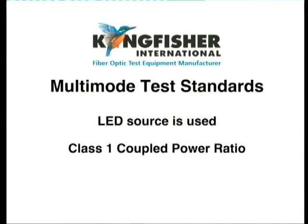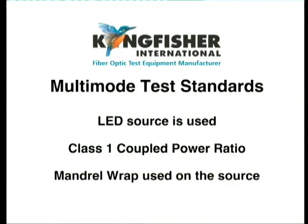Second, the LED source is selected to ensure that the light fills the entire fiber core. This is termed a Class 1 coupled power ratio. Third, a mandrel wrap is used on the source patch lead to remove unstable modes from the outer edge of the fiber core. This does mean that the measured loss may not be the same as that seen by an operational system. However, this compromise is required to achieve measurement repeatability.